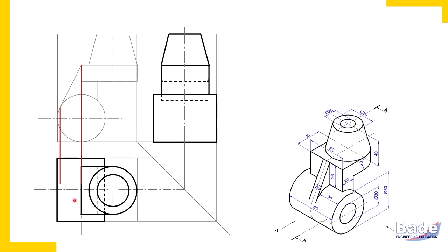So this is how we have drawn those two projectors. Now here symmetrically you measure thickness, 6 plus 6, that is 12. Thickness, watch here, 12 millimeter. It is parallel to width axis, and width axis, that is vertical in the top view. So in the top view width is vertical, so measure vertically 12, symmetrically that is 6 millimeter above the center line, 6 millimeter below the center line. So this dark line here, it is 12 millimeters long, and complete the rib. So between end projectors, exactly between the end projectors, that rectangular strip here.